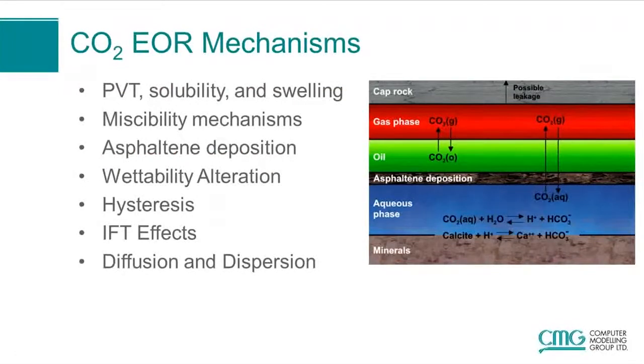Carbon dioxide EOR is a complex process, and there are so many different mechanisms involved in this technique. When the carbon dioxide is injected into the reservoir, it dissolves into the oil, and at the same time it can partition into the water phase. Under a specific temperature, pressure, or composition, we may have asphaltene precipitation or reactions in the aqueous phase.